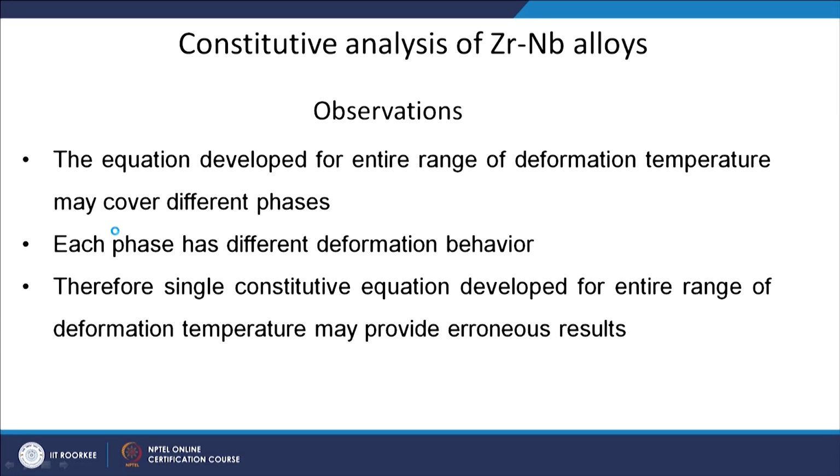The observation we found from the literature is that the equations developed were for the entire range of deformation temperature, which, as I told you, covers different phases. Each phase has different deformation behavior. Therefore, a single constitutive equation developed for the entire range of deformation temperature may provide erroneous results.